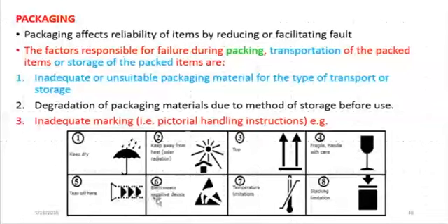If you see something like this, it is showing you the direction in which you should tear to open the package. And if you see this sign of a hand, it is telling you that your device is very sensitive to electrostatic. Therefore, don't touch it with your hand. There may be static electricity in your body that can discharge and damage it.